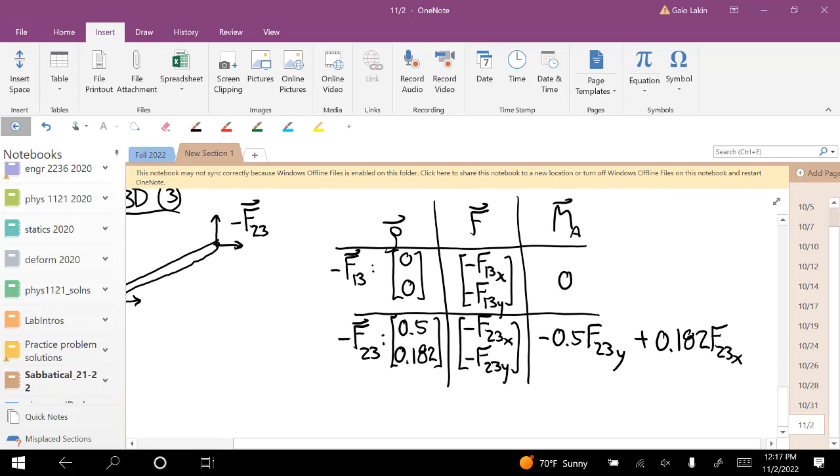By the way, this thing, like I was saying before about the two force members, this is also a two force member. And rotational Newton's second law here says that add these up is equal to 0, which has the effect of saying that those forces have to act along the line of that thing, you know?